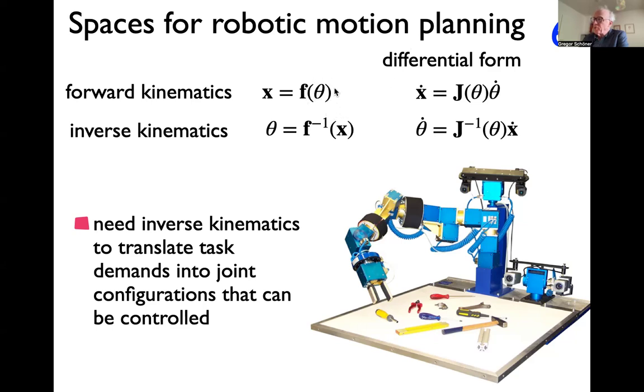And so that description of these variables you can control, that's the joint configuration, the vector theta, while the things we're interested in are typically positions of tool points. This is like the hand. It's sometimes called the end effector. Could be the tip of a welder, or the tip and orientation of a spray can, and so on, depending on what you do with a robot.